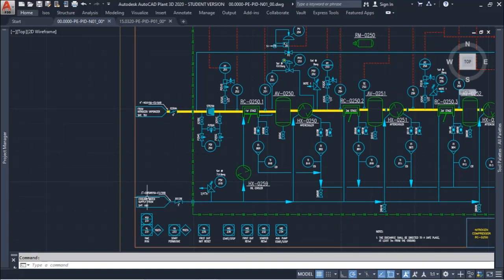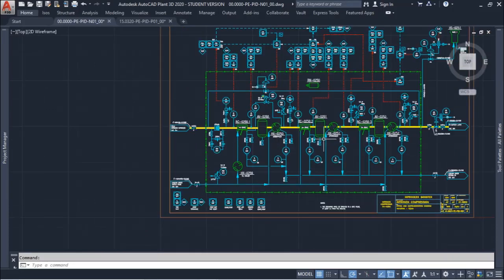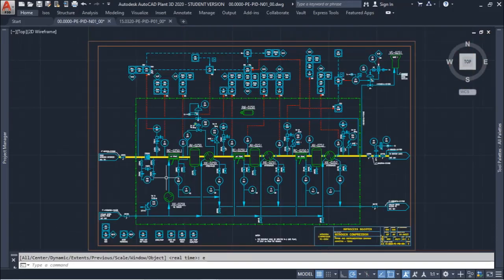So the cooling water line is a secondary step in your process, and the thicker line is the main reason for the process. So my first tip to you is to take a look at the flags and the arrow direction, because they will tell you what is the starting point and the ending point of your process in the P&ID that you are reading.